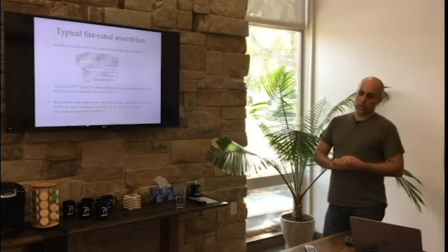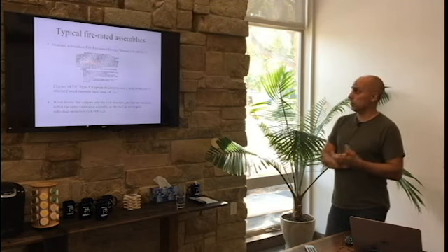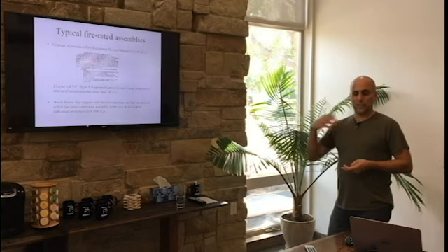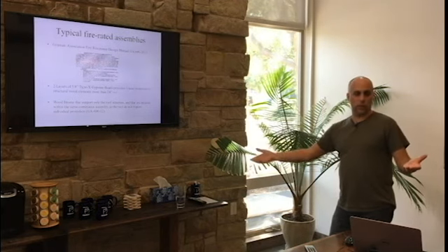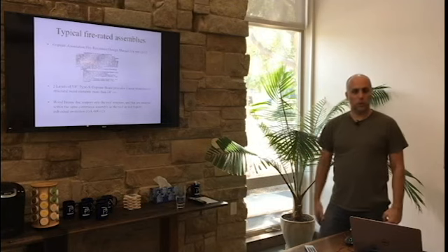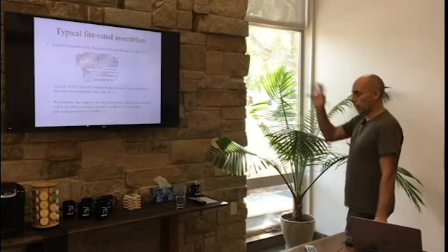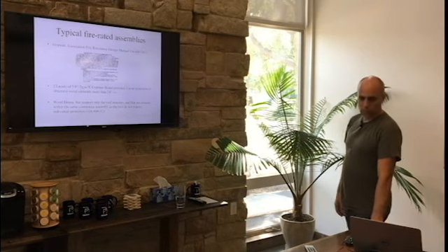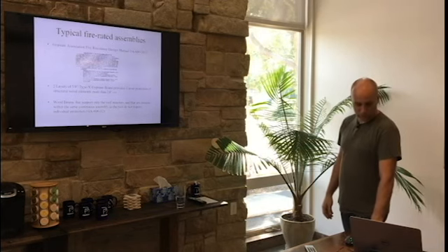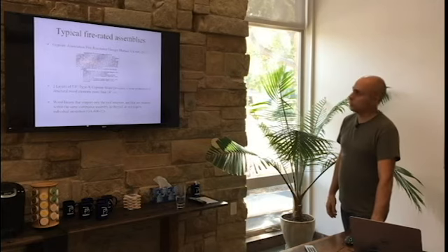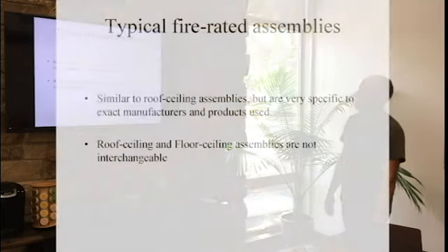It's now in that Gypsum Association's Fire Resistance Design Manual, which the IBC references directly and says everything in there is as included herein. So it might as well also be in the building code. And actually, no, it is, because it's directly referenced. So now 2 layers is official. We're not just making it up or basing it upon a report. It's now in one of the industry recognized ones. So we've talked about that.